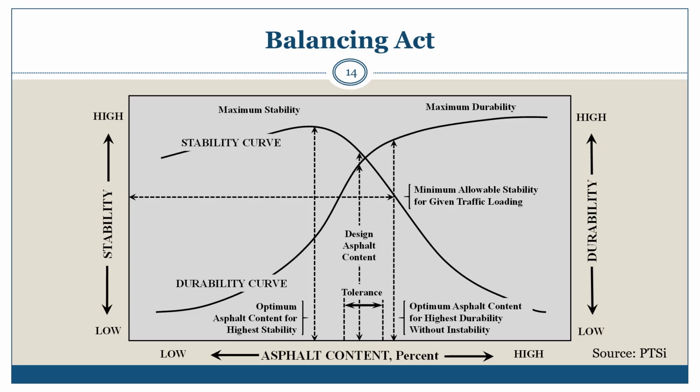Regardless of design method or application, the design of asphalt mixture is a balancing act combining selection of aggregates and asphalt binder proportion to provide desired performance. Asphalt mixtures are designed to provide workability necessary to construct an in-place pavement resistant to permanent deformation, fatigue, low temperature cracking, and moisture damage, as well as provide a skid-resistant, smooth-riding, durable surface. Of primary importance in achieving the overall performance goal of effective asphalt mixture design is asphalt binder content.